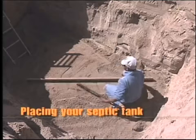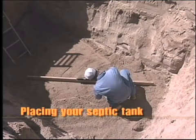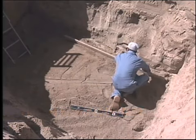Carefully level the bottom of the hole before the septic tank is in place. This will make tank installation easier. Level the septic tank hole using a 2x4 and carpenter's level.